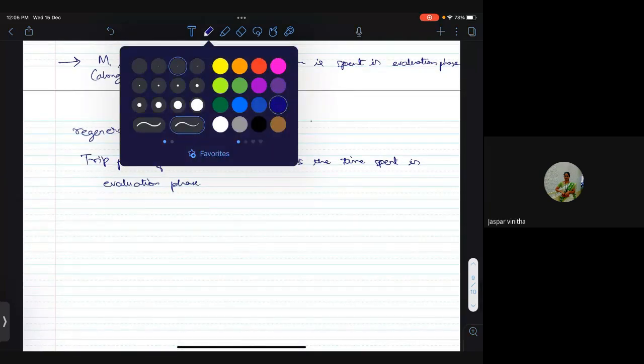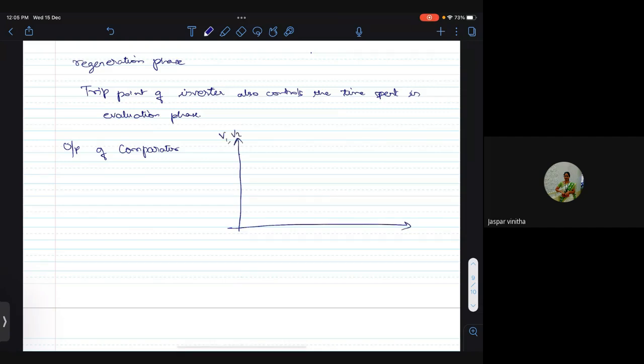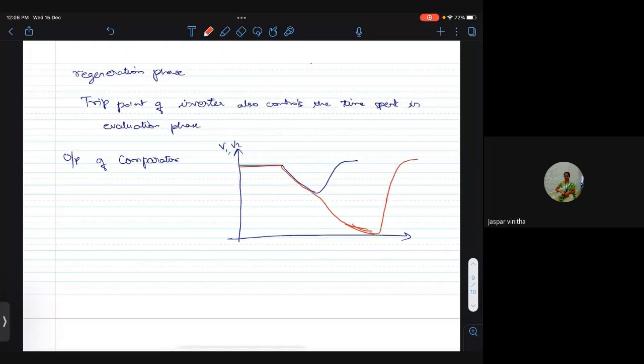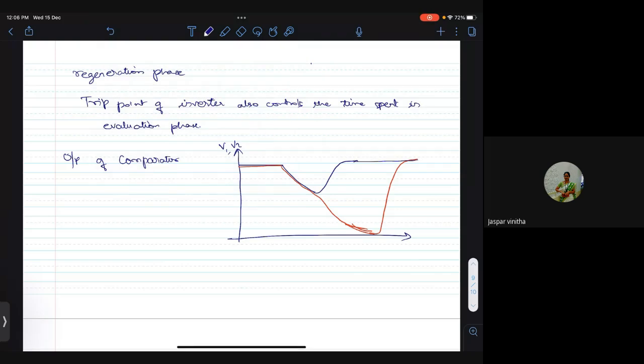Now the output of this comparator is nothing but V1 and V2. In the pre-charge phase, it will be pre-charged to VDD, and then they will come down and go back to VDD like this, or come down and relax to go to 0 like this. And in the next phase, again, it will be pre-charged to VDD. Okay, so this is not a proper digital logic.